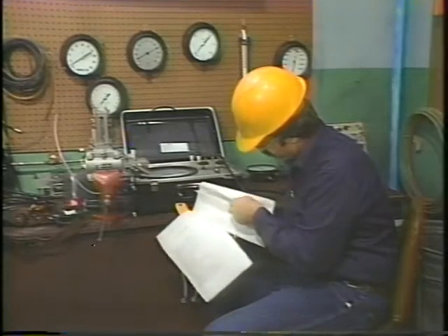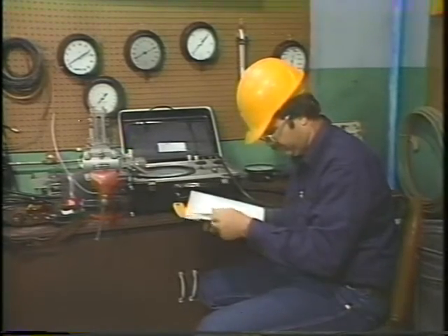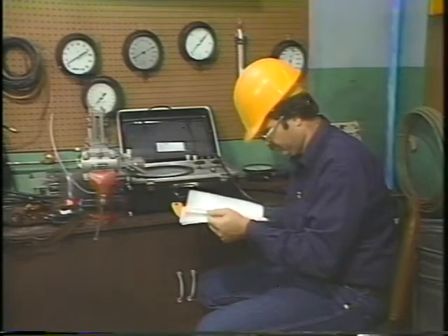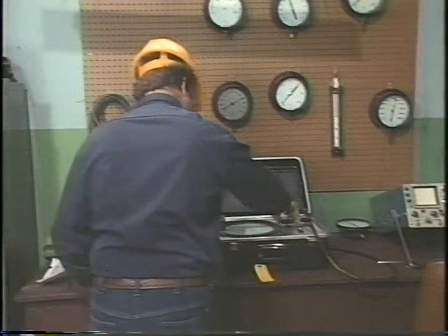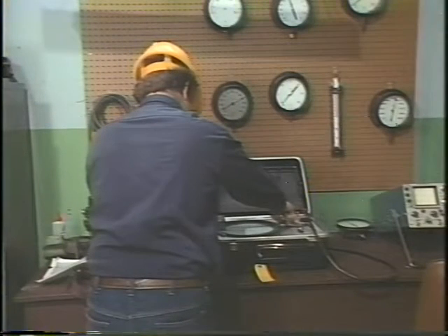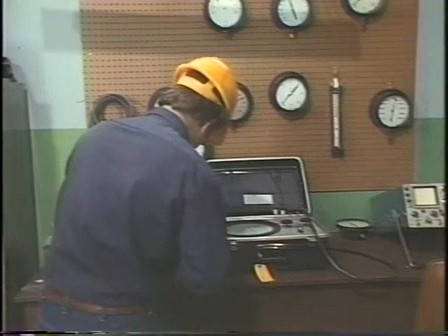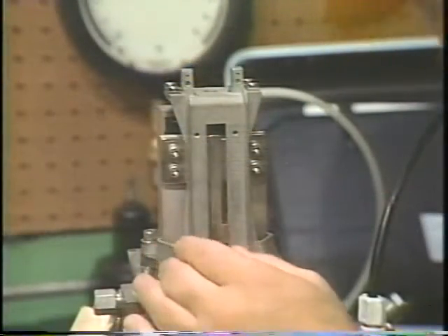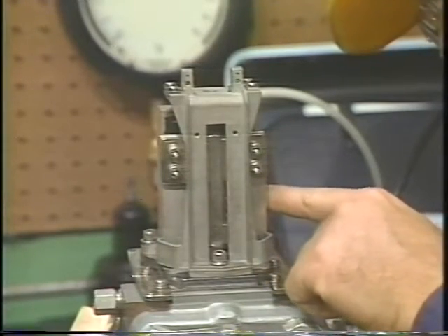So it's on page 21. See, the manual says to push the vane close to the nozzle. If the vane-nozzle relationship is okay, they should be parallel with each other. I'll apply a mid-scale pressure so that the transmitter is operating under its normal conditions. Let me see how that relationship looks now.